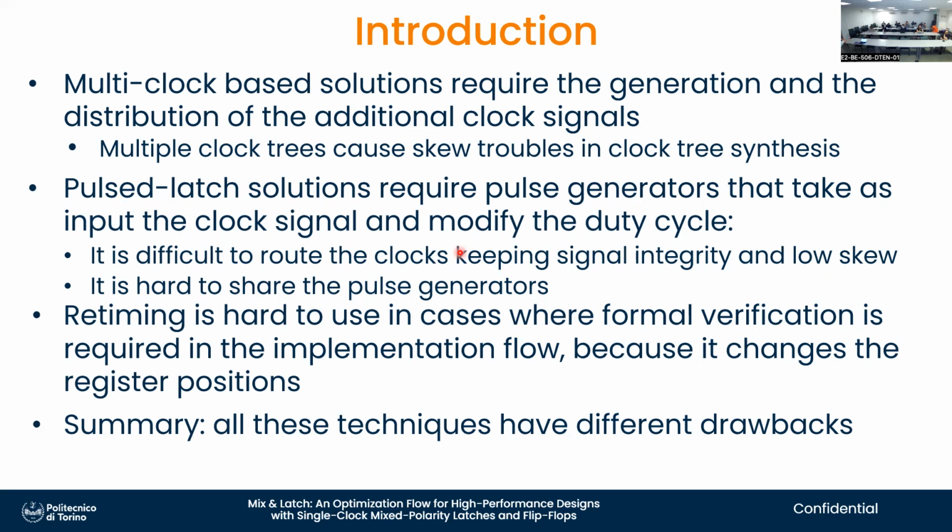It's easy to do for an FIR filter, for example, because all the stages are the same, the logic is the same, easy. In a microprocessor, the first stage does instruction fetching, which is not too complex. The second one does instruction decoding, which is very complicated for a complicated instruction set. The third one reads the data, which is again simple. The fourth one does arithmetic computation, which again is computation intensive. So it's hard to balance those stages. So people use multi-clock based, where you can borrow time from an easy to compute stage to a hard to compute stage. However, we have